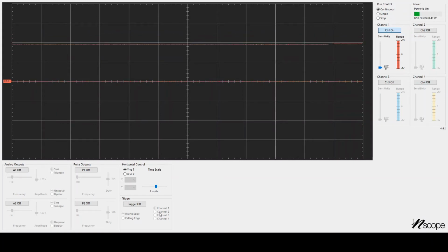So the problem is that what the oscilloscope is doing is it's grabbing data, it's plotting it to the screen, and then it's grabbing more data, it's plotting it to the screen. But the actual time it takes to plot it is much longer than the data acquisition time. So normally we're just going to miss it. We're never going to see the event. It's just so unlikely that when we push the button, the scope was actually reading at that moment. So there's the ability of a scope called a trigger. So I'm going to turn trigger on.